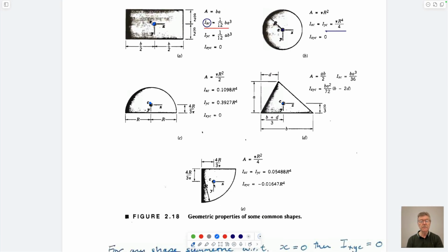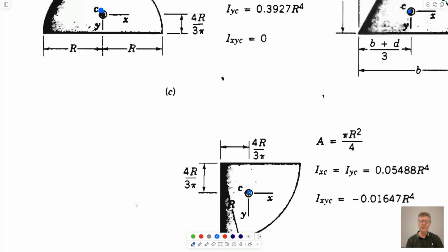The C is the location of the centroid. And so if you had a quadrant and you put it on your finger, this would be the point that it would balance against. And the idea is that you integrate over this whole surface. You probably don't really care. You integrate all the little differential areas, dr d theta, multiply each by its little piece of weight, and you look at the lever arm, which is this length here, and when you sum those up on the whole disk, the one point where those all sum to zero is the point that it's supported by.